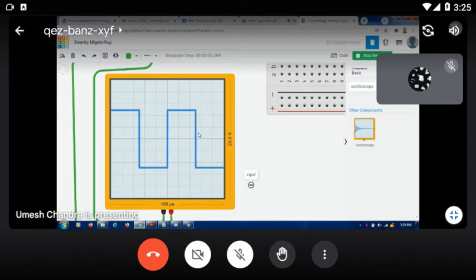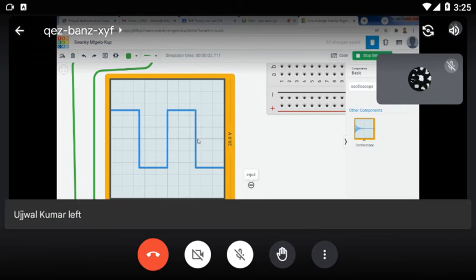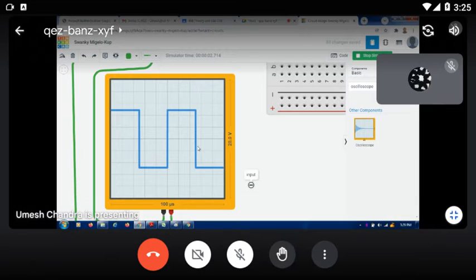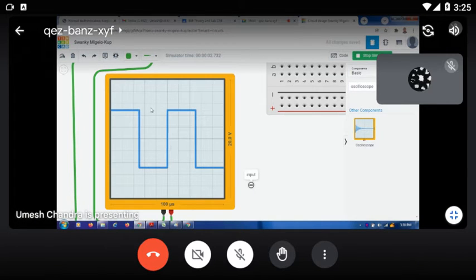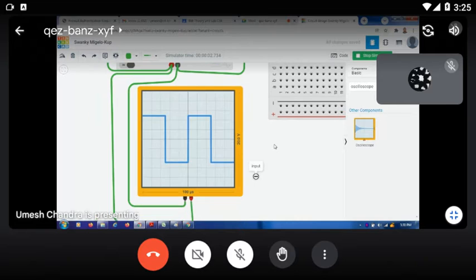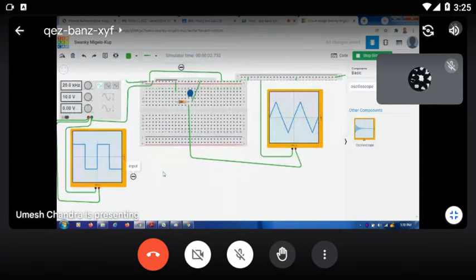Now you calculate: one big block, another big block, then another half. That means 2, 2, 4, and half is 1, so 5. The lower side is the same: one big block, another big block, that is 2, 2, 4, then another half. Half means 1, because one block is 2 volt, so half of the block is 1 volt. Lower side is 5 and the upper side is 5 volt, total 10 volt. Okay. In the same way, for the output case, what is your voltage?